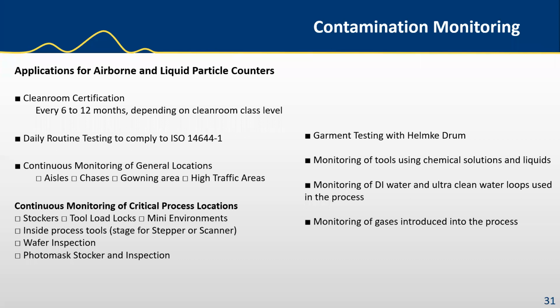Here we see some applications of airborne particle counters used in a wafer fabrication facility. Cleanroom certification, you can use the portables. Daily routine testing to comply with ISO 14644 Part 1, again with portable units. You can have continuous monitoring of general locations, the aisles, the chases, the gowning areas, high traffic areas where people are going to be,